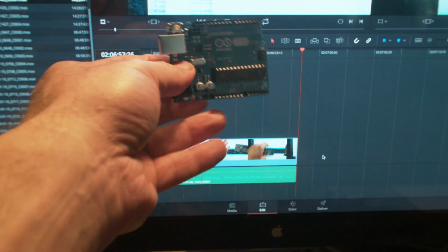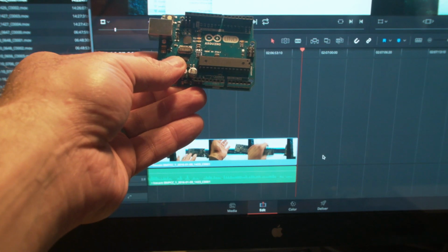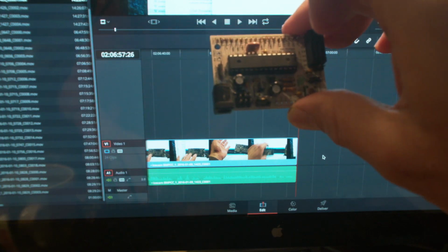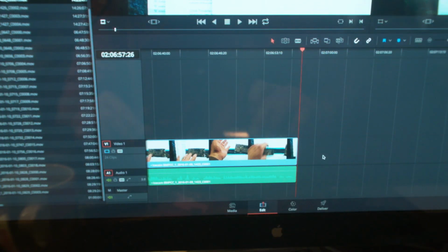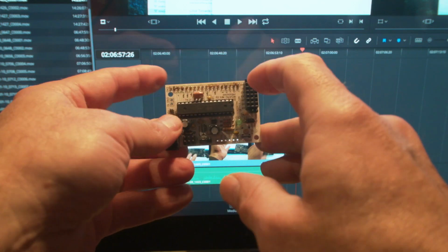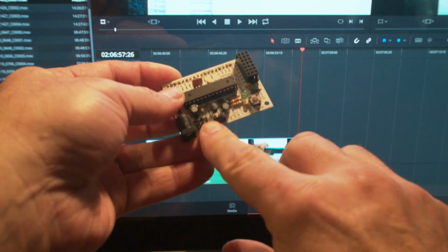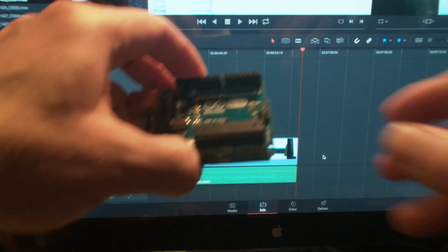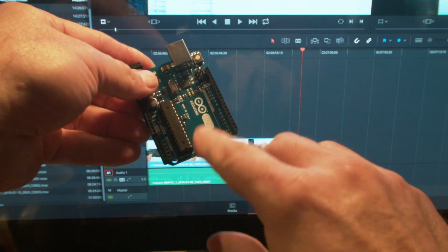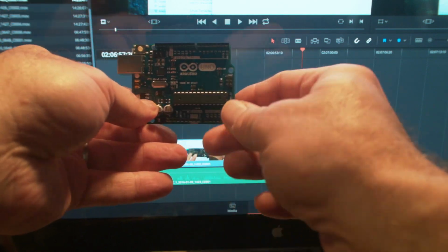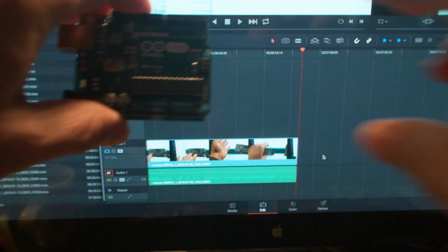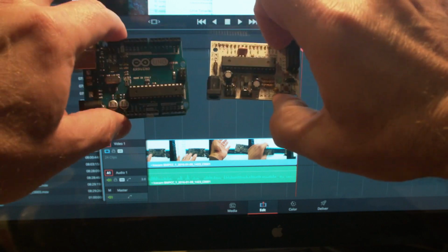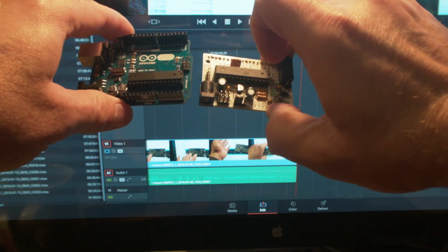Then we talked about the Arduino style microcontrollers in general. And we talked about all the different types of Arduinos we could have. We talked about Freeduinos. We even discussed how to program a Freeduino using these little 6 pins here, which are the ICSP pins, which appear even in a regular Arduino UNO. Actually, you could program that with the in-circuit programmer as well. So we showed how you could do things with an in-circuit programmer. We showed how the different Arduinos will run the same code using the same IDE.